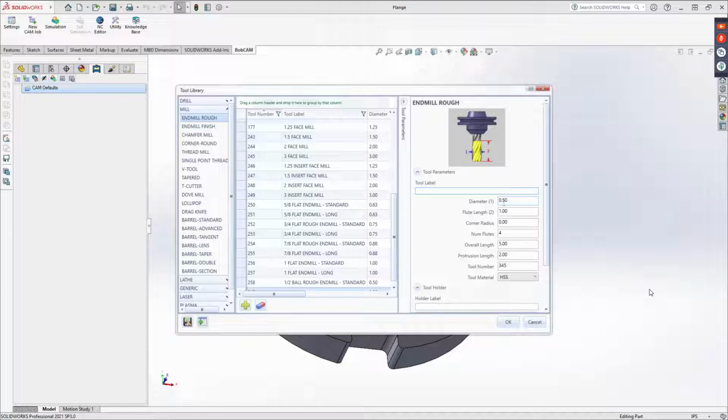We will actually generate tools automatically for you though. So let's say, for instance, you do a drill and it's a 3-inch depth. We're automatically going to generate a tool that will accommodate that. Same thing with 2-axis. If you give us a depth of 2 inches for a cut, we're going to make sure that the tool that you have automatically selected can do that. It doesn't mean you can't go and select a different tool.